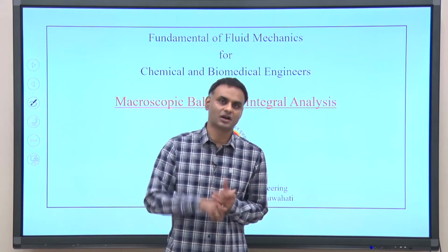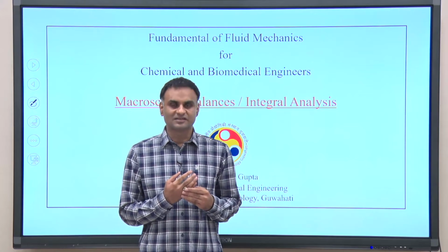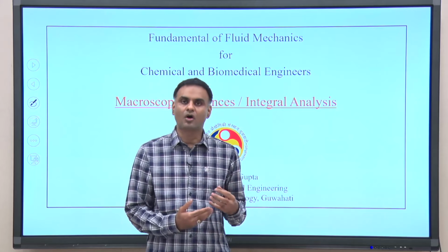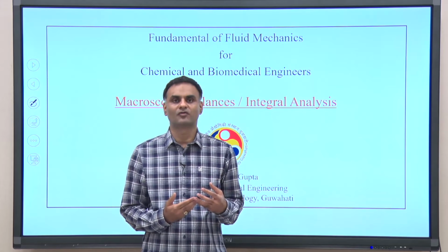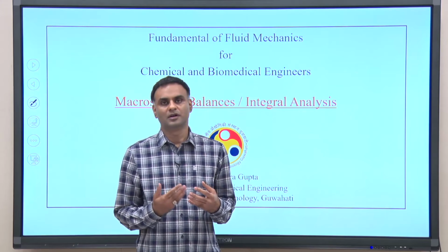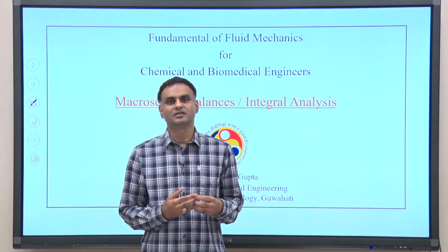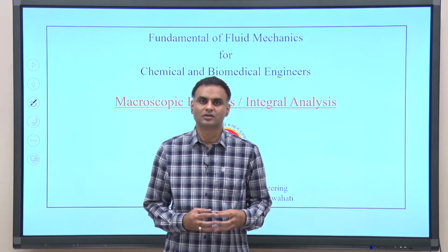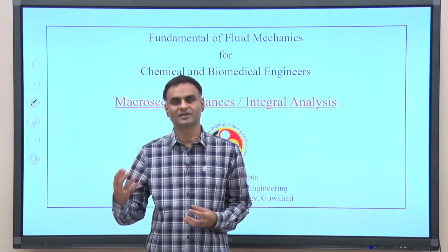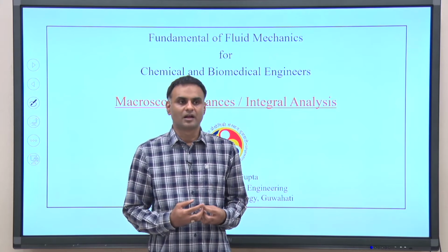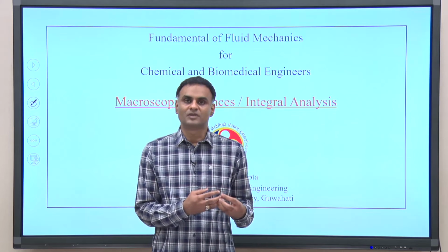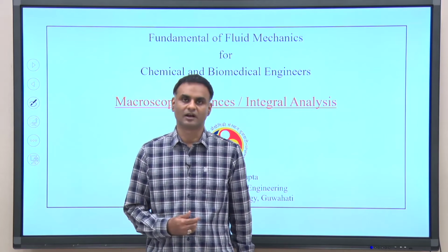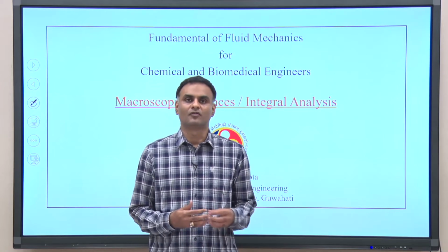The number one was dimensional analysis. Here we can list down all the parameters on which the flow depends, and then using dimensional analysis we can find out the relevant non-dimensional groups and identify the independent parameters on which a dependent parameter will depend.